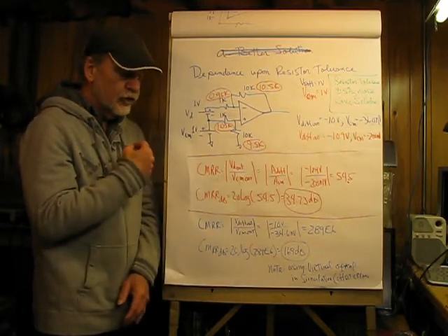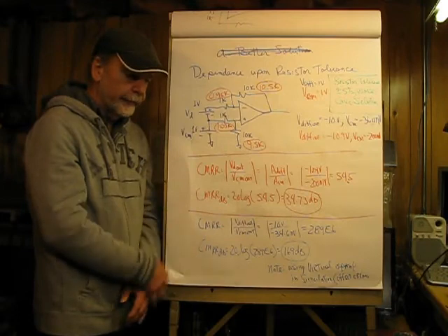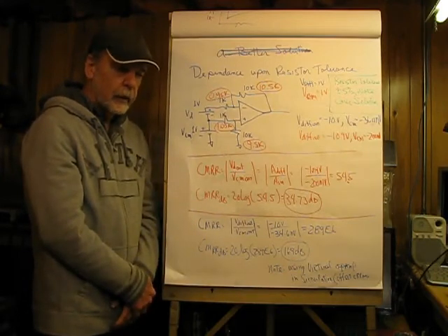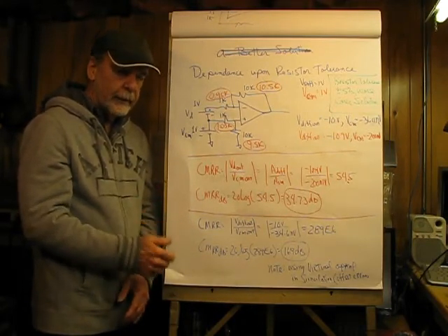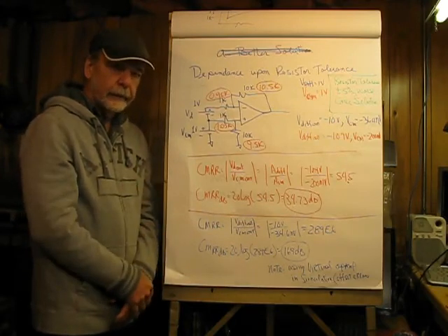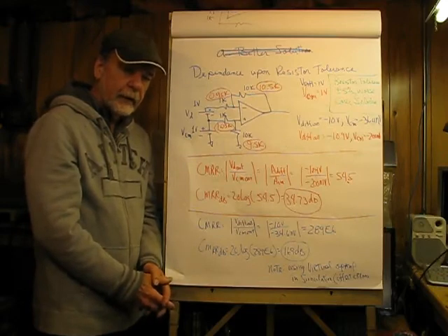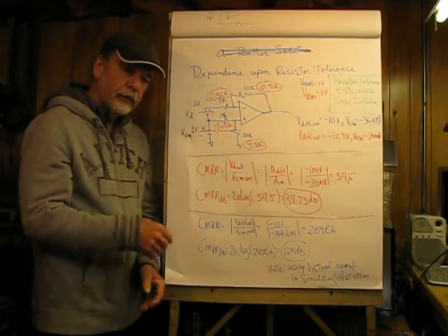So just the shielded coaxial cable, this was twisted pair shielded, had enough ingress so you could actually hear a hum. And when I say hum, I'm referring to either 60 Hertz power line or possibly 120 Hertz, based on the fact that we have rectifiers and things like that, bridges for example, that do have 120 Hertz output as their fundamental frequency.